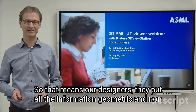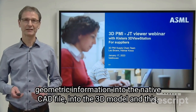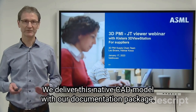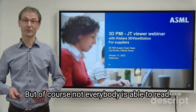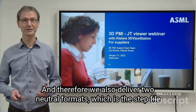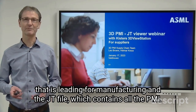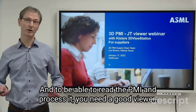So that means our designers put all the information, geometric and non-geometric information, into the native CAD file, into the 3D model. And therefore we always deliver this native CAD model with our manufacturing documentation package. But of course, not everybody is able to read NX files. Therefore, we also deliver two neutral formats, which is the STEP file that is leading for manufacturing, and the JT file, which contains all the PMI. And to be able to read the PMI and process it, you need a good viewer.